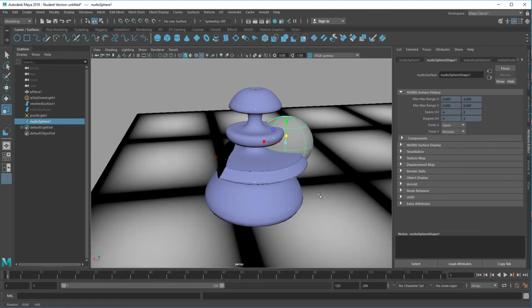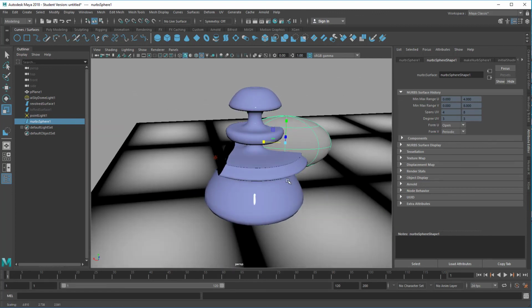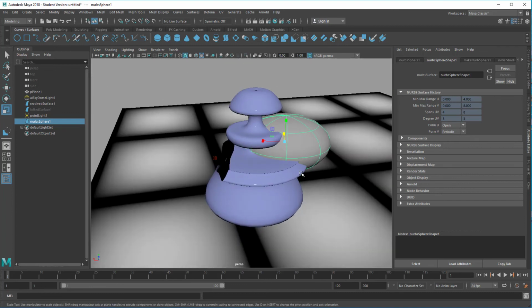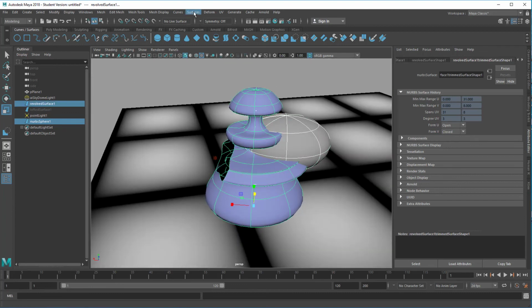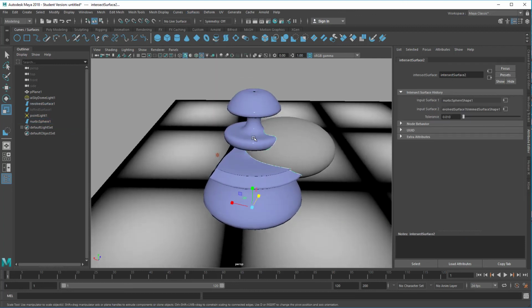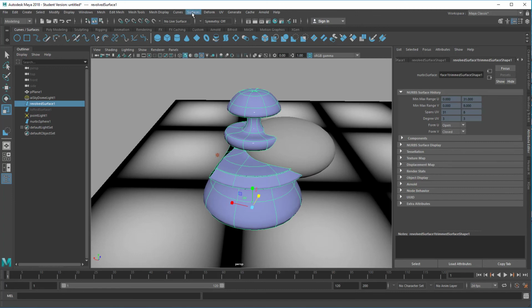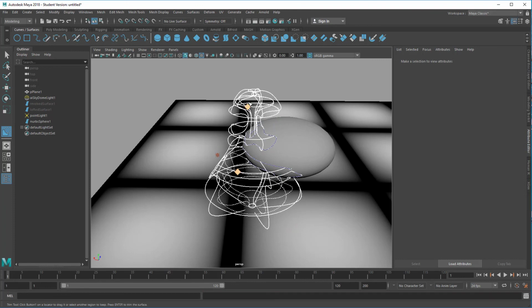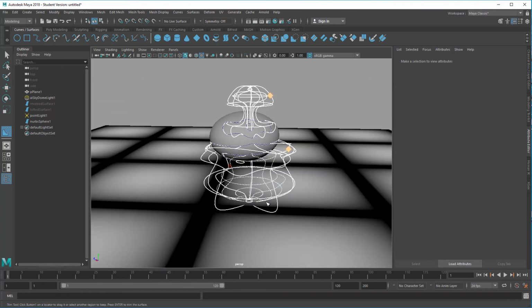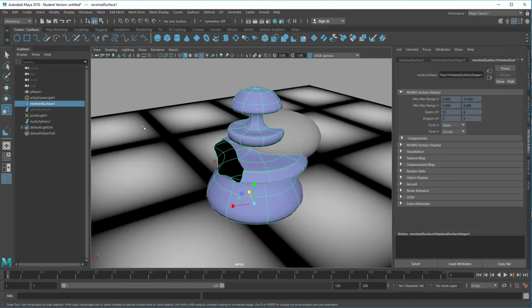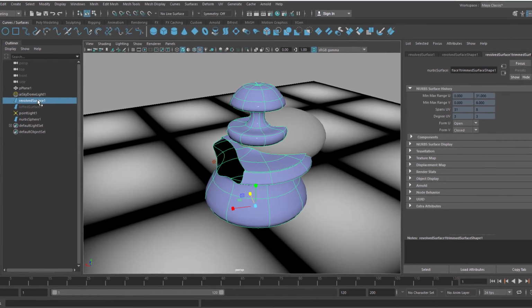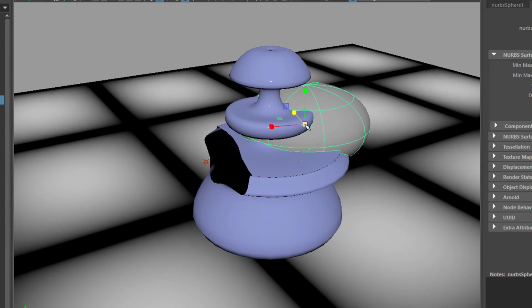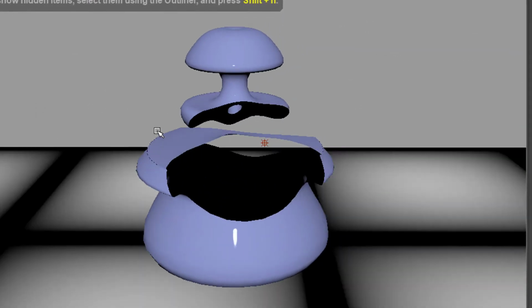And since I don't want to keep it, I just do another cut, which is called a trim in the NURBS world. So I select these two surfaces, Surfaces, Intersect. Now I select this surface because that's the surface I want to keep. Surfaces, Trim tool. I want to keep this part and maybe the inside part as well. And then I punch in Enter. And when I hide this sphere now, I get this cut.